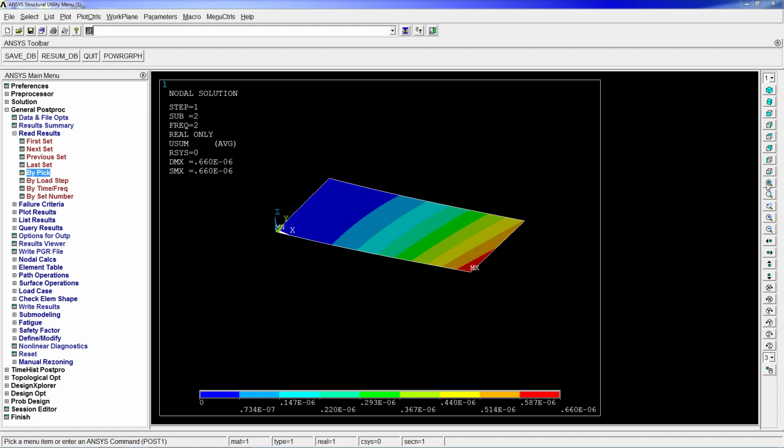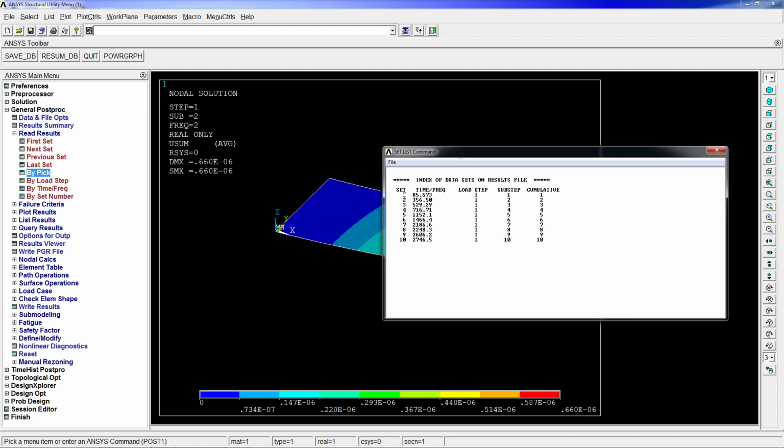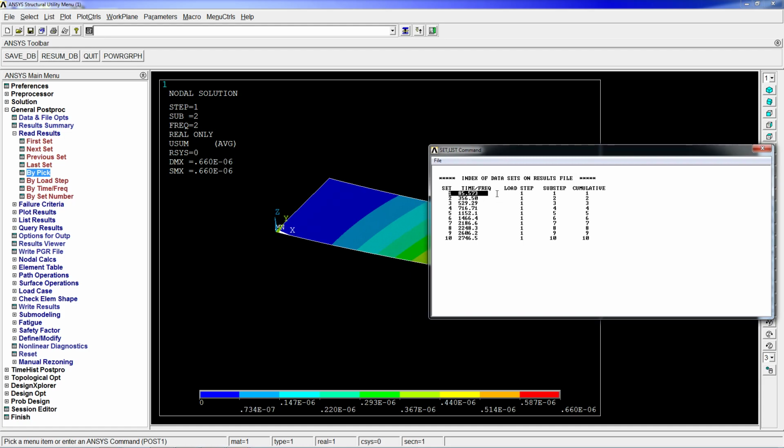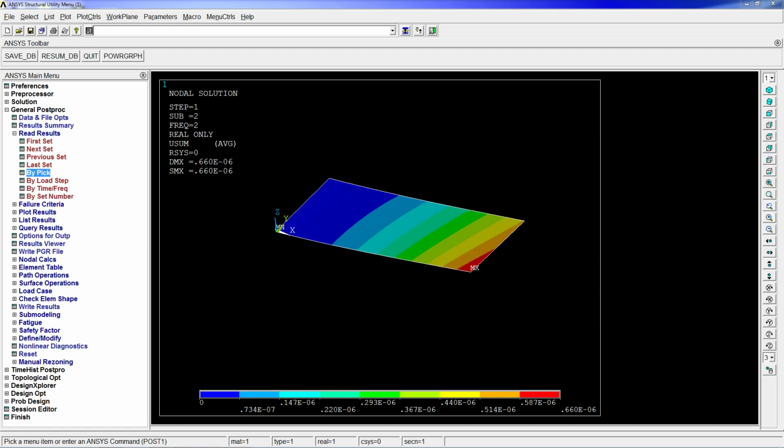So here we're going to look at, for example, 85 hertz. One of the things is that because we've been using a step increment of 1 hertz, we can look at these values, but we're not going to be able to catch the 85.537 frequency because we will be either on 85 or 86. This should be good enough in most of the simulations. If you need to obtain a specific or very detailed effect of a certain frequency, you will have to perform a simulation between 85 and 86 hertz and check how important this peak is for, I don't know, 1,000 values between those two frequencies or something like that.